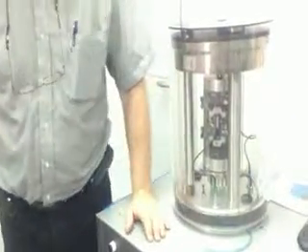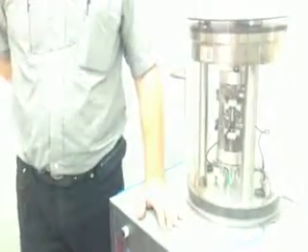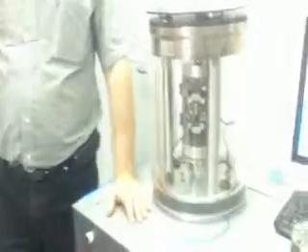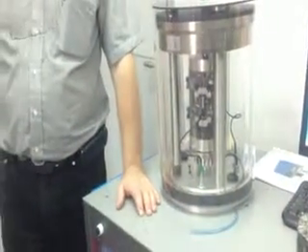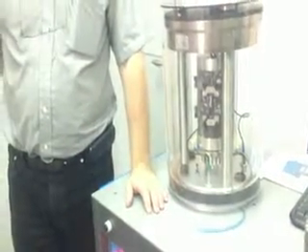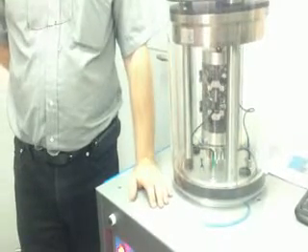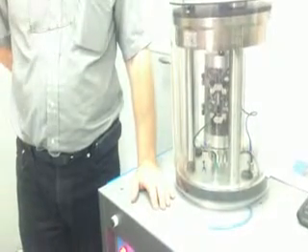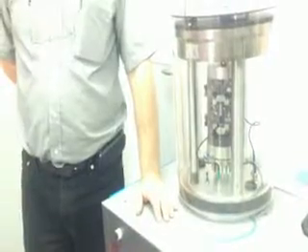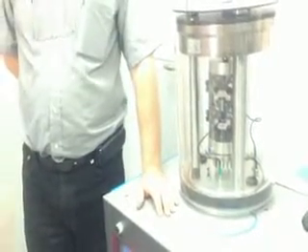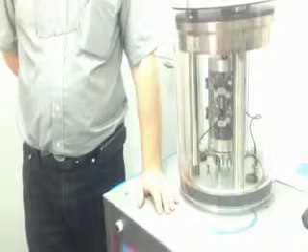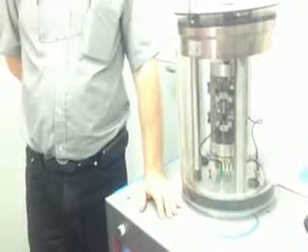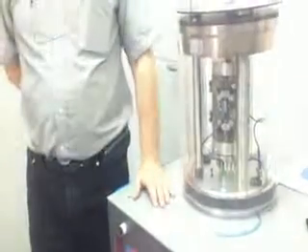Also, you should remember that most of the tests you have replicates, 3 to 5 samples. So you want to run all your tests for all the samples at the same temperature before you move to another temperature. Because you don't just run for one sample, you run for 3, 5, 10 samples. So you finish all the samples first, and then you condition and run the test. We can keep it in the oven, but we cannot condition only that one sample and get it warm up. That's why we have to condition these 3.